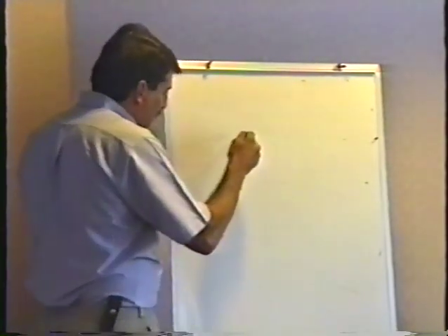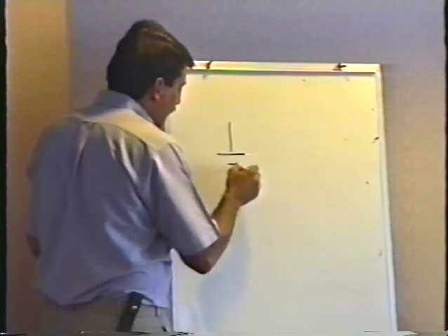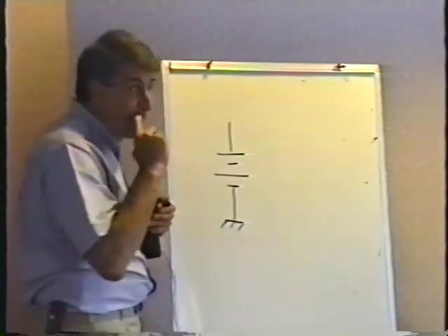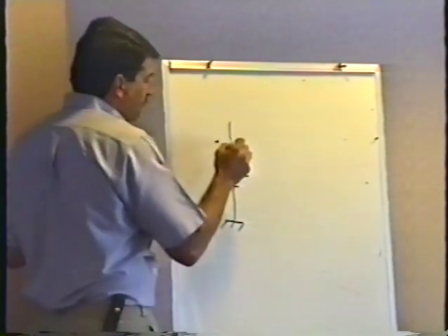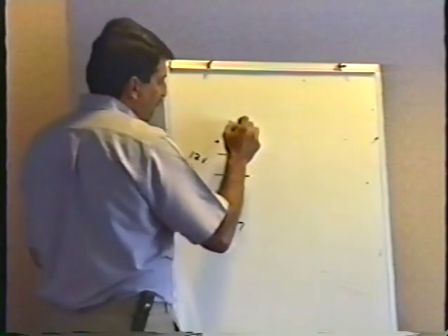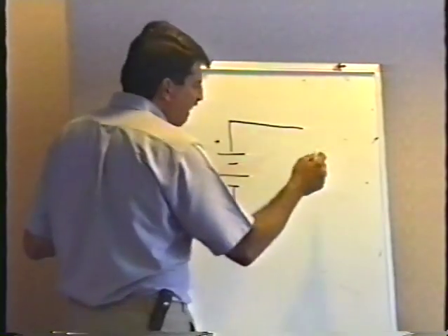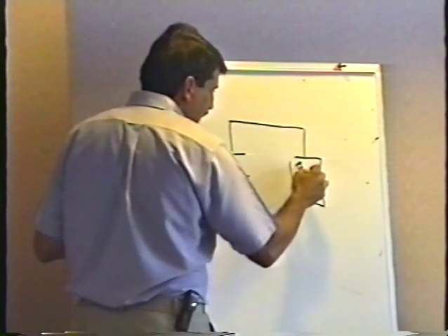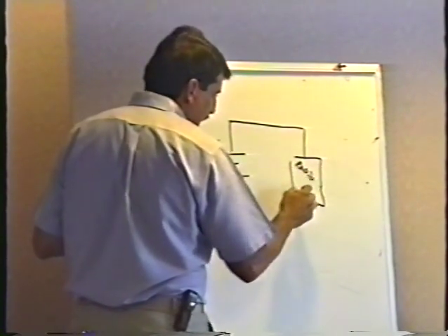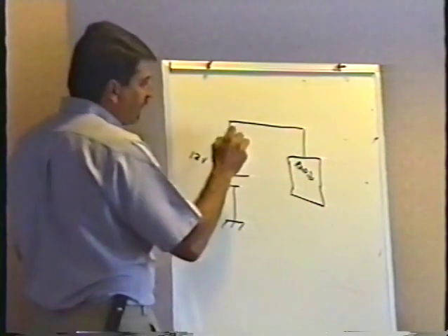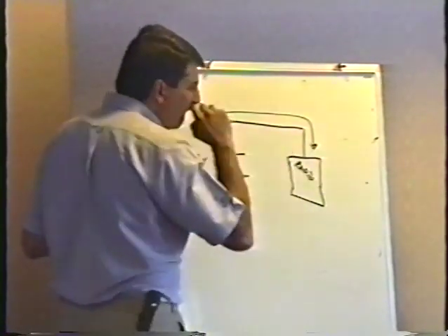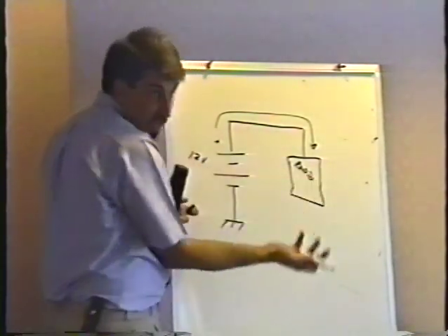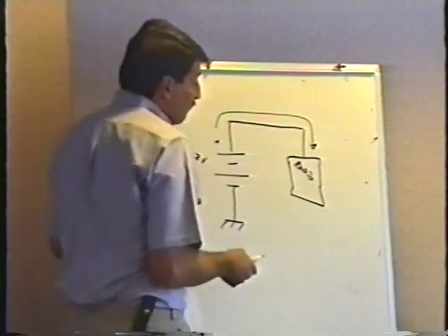Let's go back to our car here, automobile. Here's the 12-volt car battery. The negative side is connected to the chassis ground. There's the positive side, 12-volt battery. It goes out here, and let's say it goes to my radio or something. There's the DC power going into the radio. That's the source path, isn't it, right? The path from the source to the load, which in this case is my radio. My source is the battery, load is the radio.